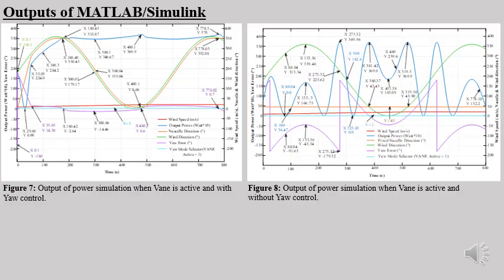But once the nacelle starts matching the wind, power begins rising, reaching about 2.8 kilowatts at 100 seconds and climbing to over 3.5 kilowatts as the yaw error becomes small. The plus or minus 15 degree dead band is visible at the flat sections of the graph.